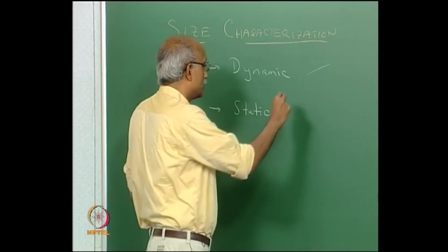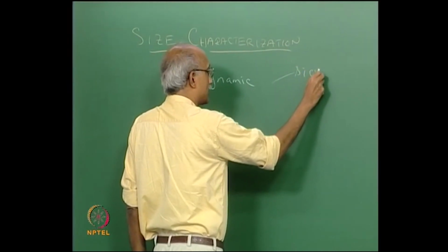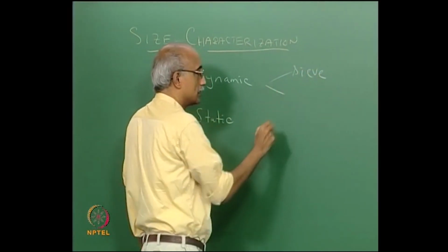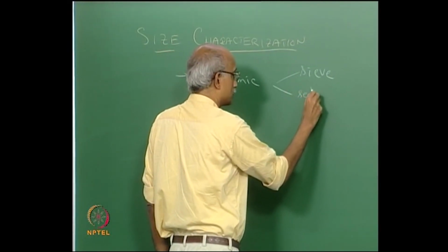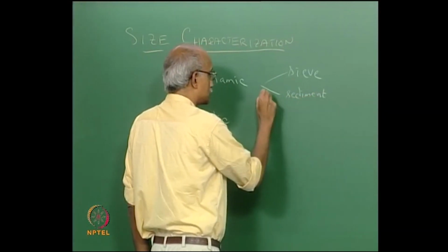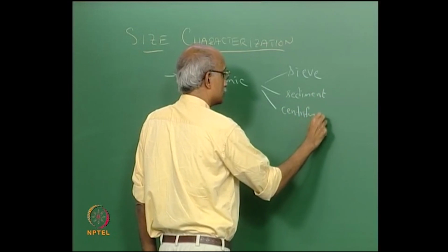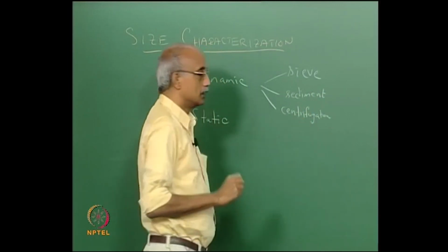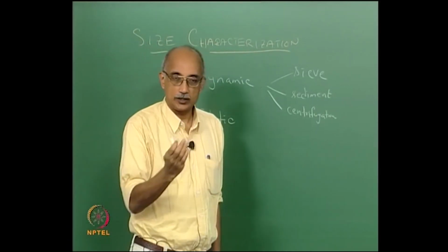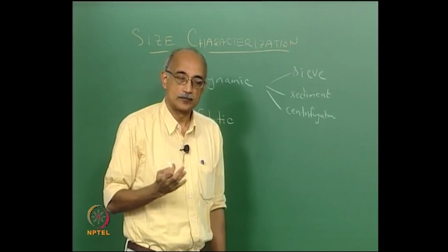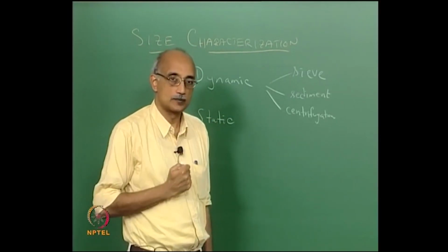So, for example, if you are doing your dynamic size characterization by sieve analysis, or let us say you are doing it by sedimentation or by centrifugation, in each of these cases the force that you use to set the particle in motion is very different, right. So, the size that you measure is also going to be relative to that force.